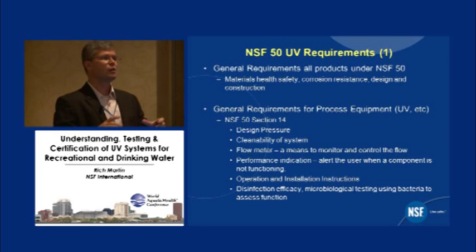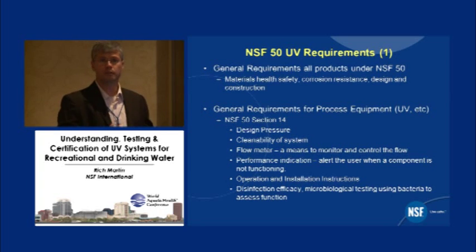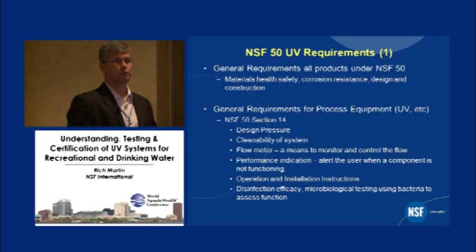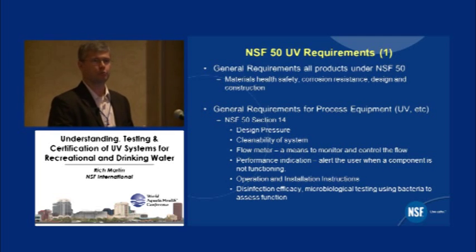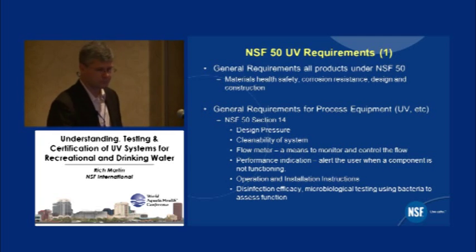You could do that, but it's going to require the installation of that UV system with a flow monitoring device that's tied to the system. Why? UV operation is critically dependent upon, obviously, some factors such as irradiance, ultraviolet light transmissivity through the water, and then flow rate. So you need to have those parameters all monitored.